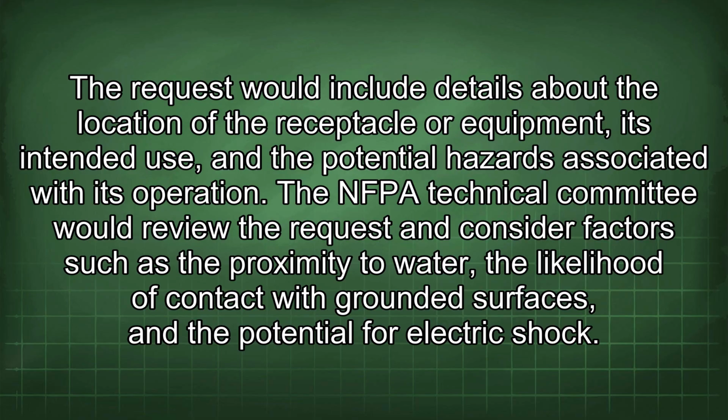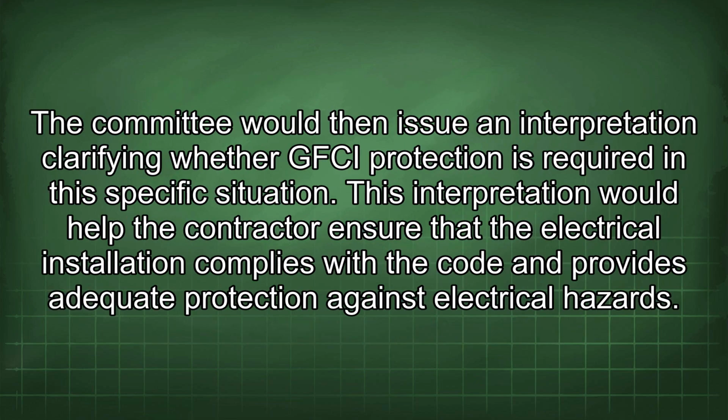The NFPA Technical Committee would review the request and consider factors such as the proximity to water, the likelihood of contact with grounded surfaces, and the potential for electric shock. The committee would then issue an interpretation clarifying whether GFCI protection is required in this specific situation. This interpretation would help the contractor ensure that the electrical installation complies with the code and provides adequate protection against electrical hazards.